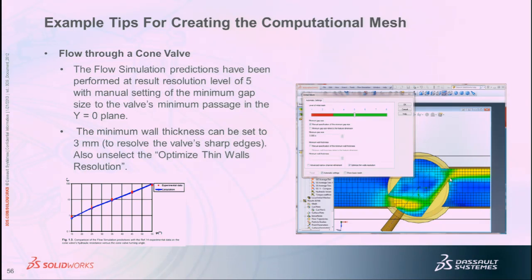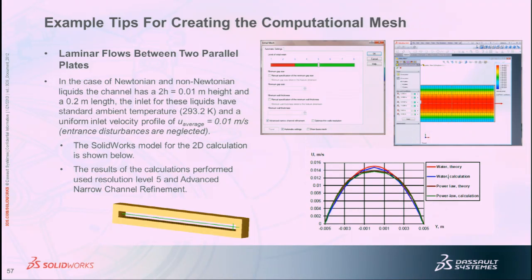If you notice, this particular valve has a very, very sharp edge to it, and they wanted to be able to capture that. So you can see the program automatically looking at the solid fluid interface and coming in here and refining all of this. So with not a lot of meshing problems, in a lot of other flow simulation, you have to set up the mesh yourself in some cases, and this would take a lot of time. But it was just basically moving slider bars and setting minimum wall thicknesses, and you can see on the left-hand curve, we were able to get very accurate results based on some test results that the customer gave us on this particular model.